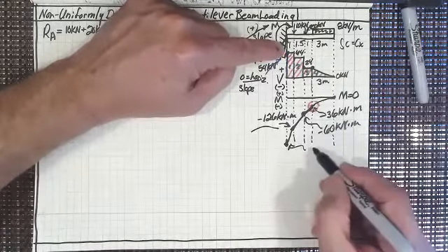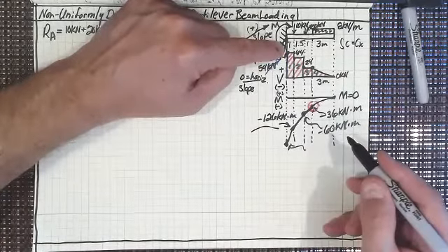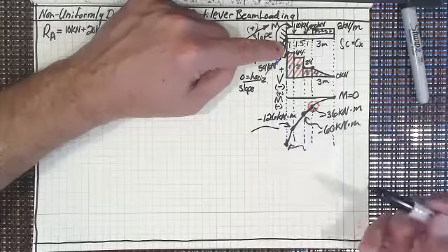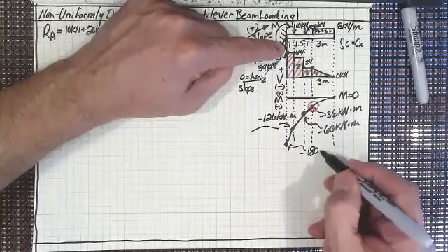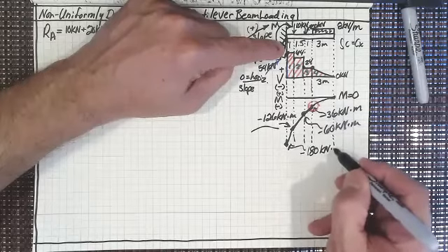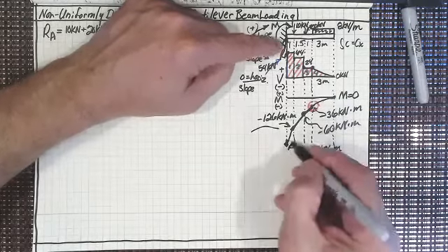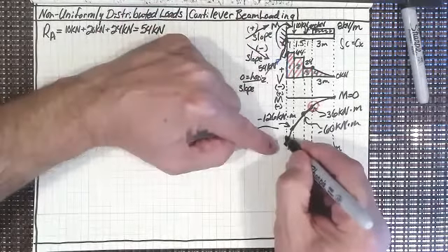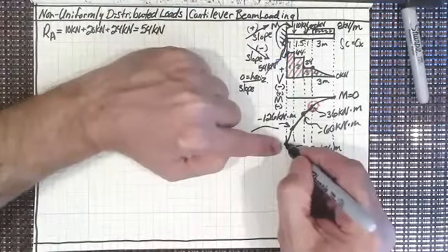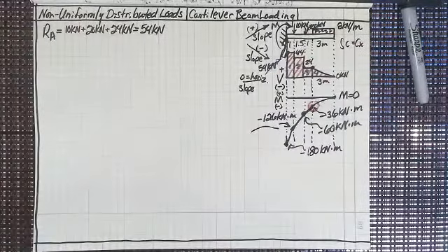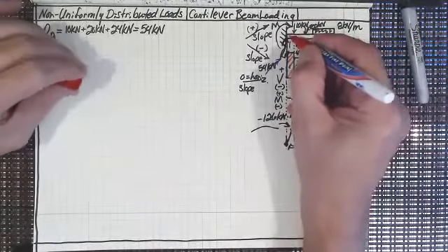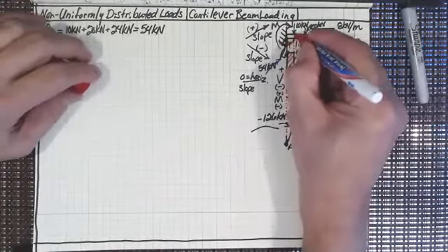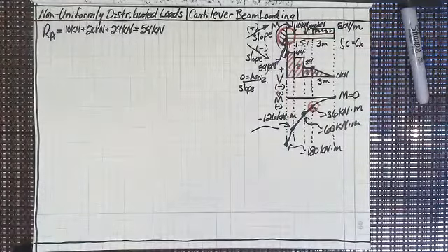And I have, just a second, 180, minus 180 kilonewton meters. And where would that occur? Of course, that would occur right at the base. And so where in the length of this is this going to be? Well, I'll tell you what, right here at the base, and this is what you would expect when you're jumping on a diving board.